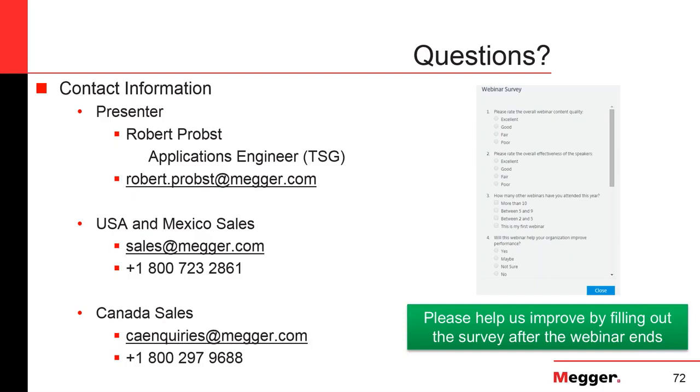If I can also add to that, running a 10 kA test in a primary injection method, these primary injection boxes run at a low voltage output. The type test that Robert's referring to, which is done in the lab, is done at full voltage, full compliance current, and full compliance voltage. So that is dangerous, and can be destructive. The primary injection test sets that Robert's talking to typically run lower voltages, typically less than 30 volts. So running a 10 kA test, you are dramatically mitigating safety constraints or electrical safeties for sure, because your voltage class is so much less.